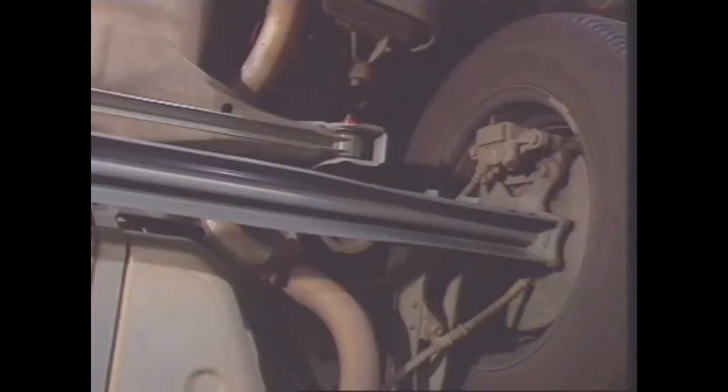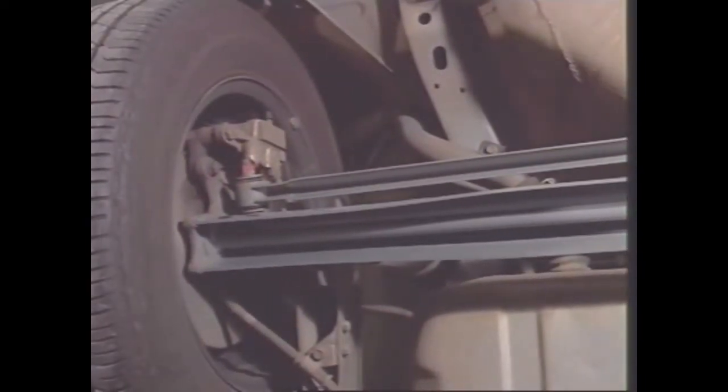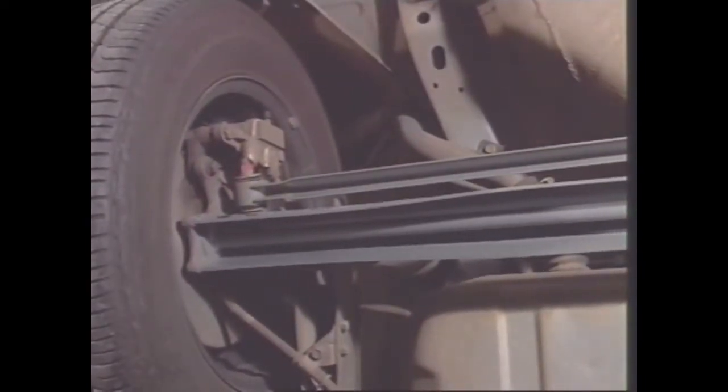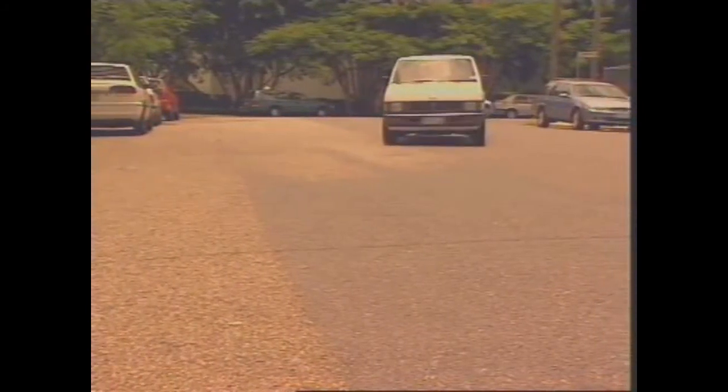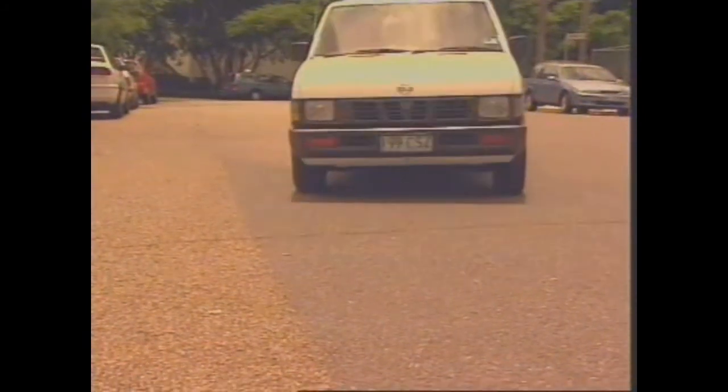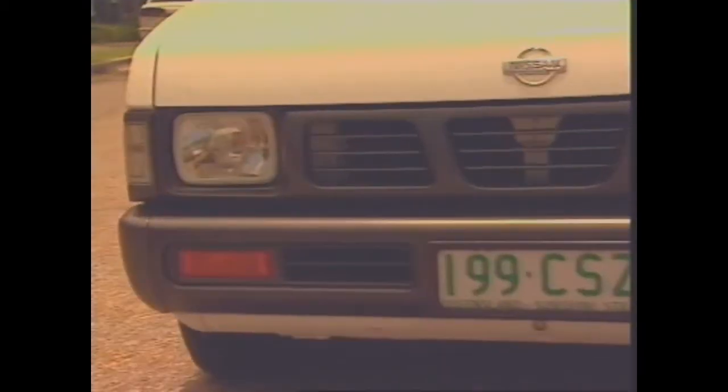Torsion bars can be used across the chassis frame on the same principle in a trailing arm suspension, or as part of the connecting link between two axle assemblies on a semi-rigid axle beam. After a lot of use, a torsion bar can sag. On many vehicles, it can be adjusted to allow for this.